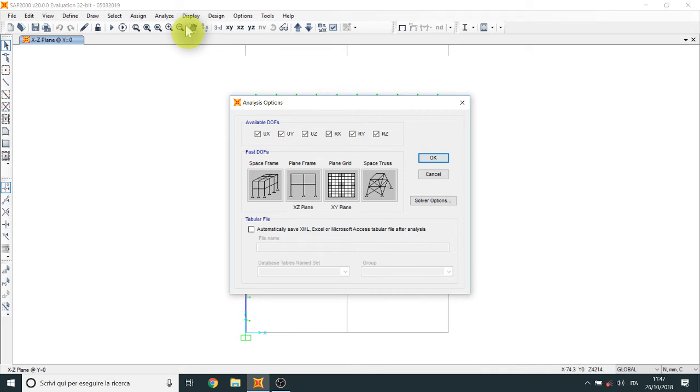This is very useful for buckling, because if you are interested only in the buckling mode on this plane, SAP will not consider buckling modes out of the plane. Of course, for our cases, it was not necessary to constrain the degrees of freedom. It is simple to pass from a 6 degree of freedom beam to a 3 degree of freedom beam.